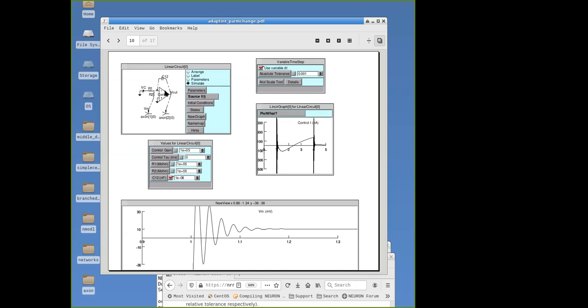Well, the problem is that our feedback amplifier has infinite gain bandwidth product. In other words, these op amps in the linear circuit builder don't know anything about an upper limit of frequency. So as fast as you're sampling time, they follow instantly. Okay. And whatever gain it has, if the bandwidth is really, really wide, you have way too big a gain bandwidth product.